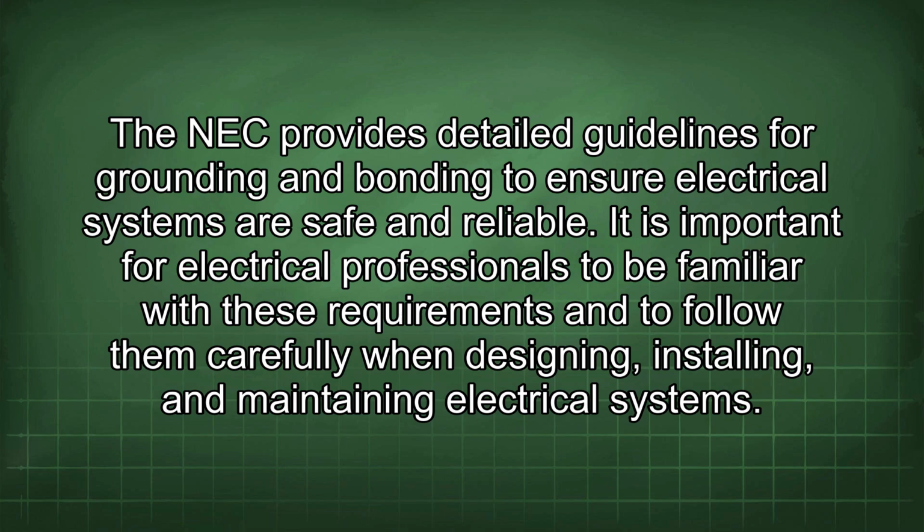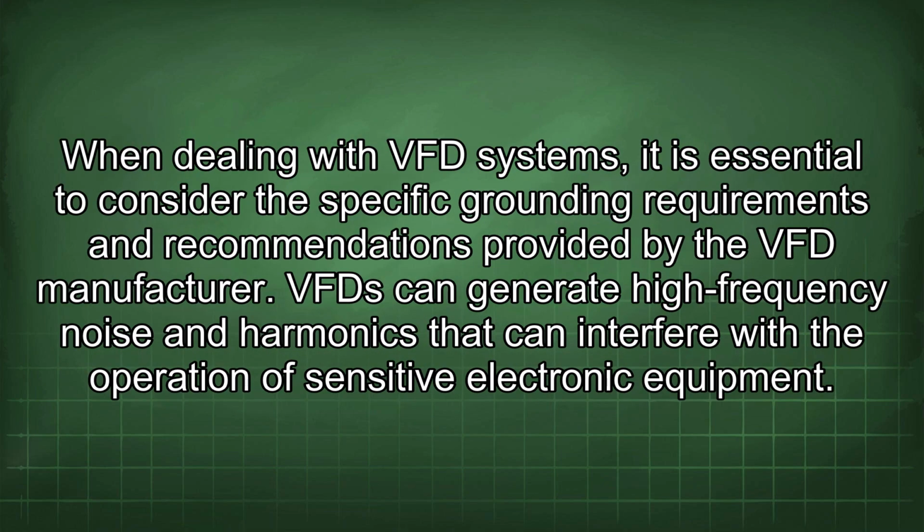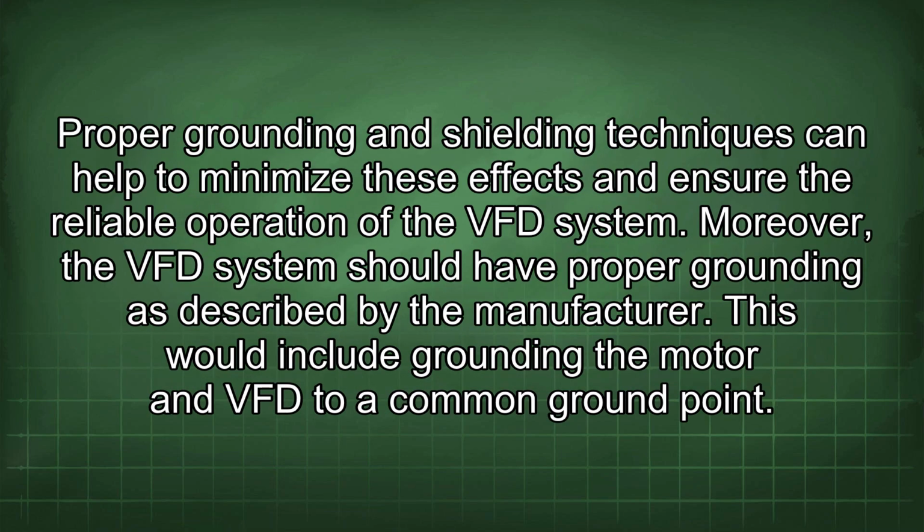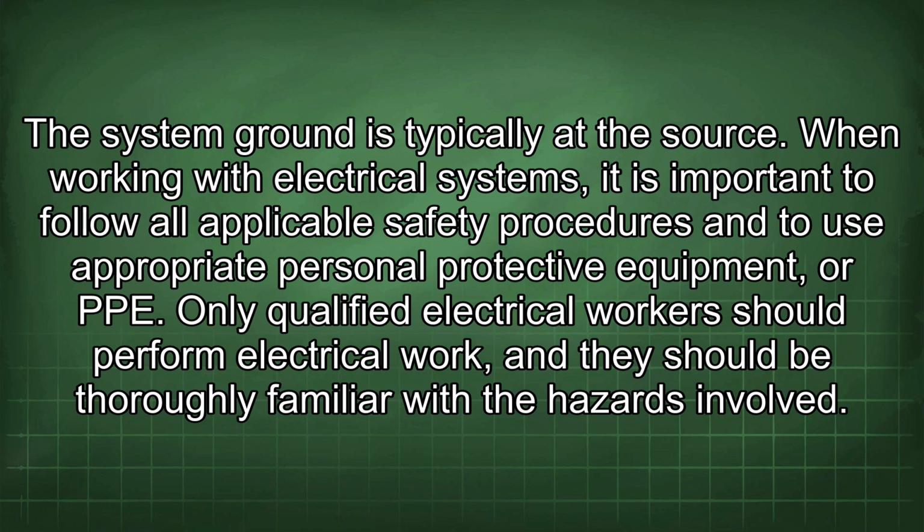and maintaining electrical systems. When dealing with VFD systems, it is essential to consider the specific grounding requirements and recommendations provided by the VFD manufacturer. VFDs can generate high-frequency noise and harmonics that can interfere with the operation of sensitive electronic equipment. Proper grounding and shielding techniques can help to minimize these effects and ensure the reliable operation of the VFD system. Moreover, the VFD system should have proper grounding as described by the manufacturer. This would include grounding the motor and VFD to a common ground point. The system ground is typically at the source.